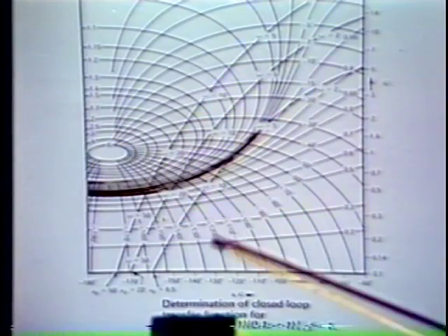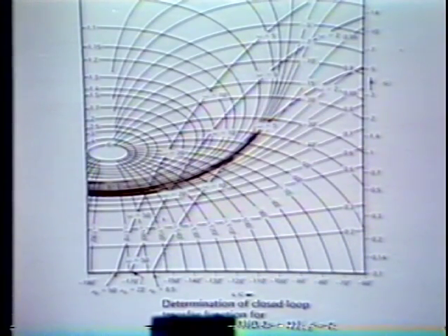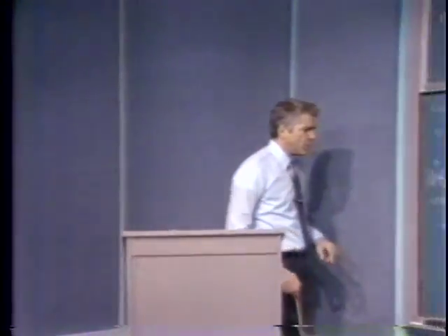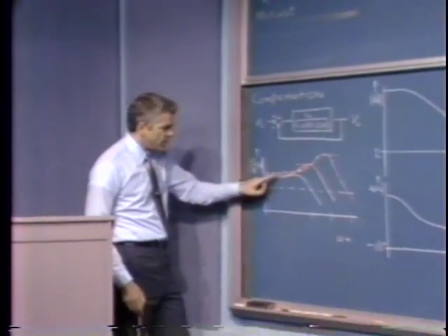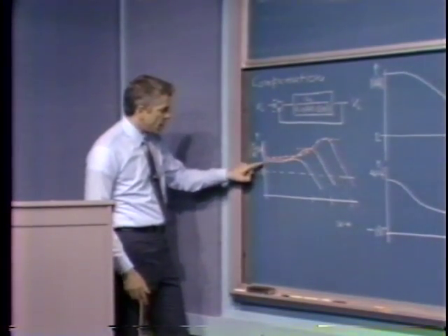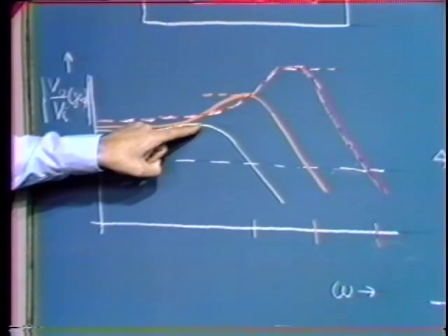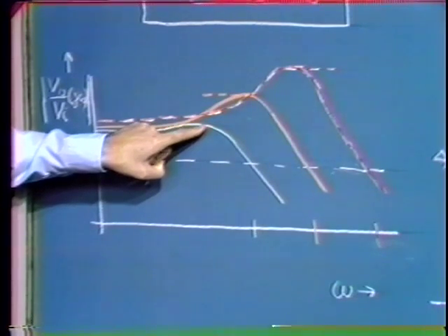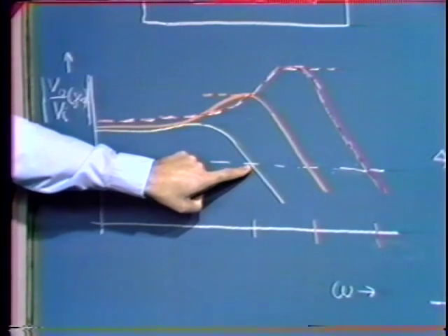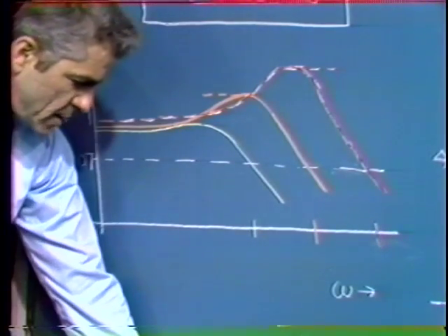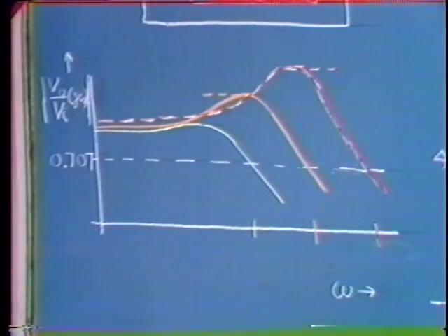The magnitude of the loop transmission is small compared to 1, and the closed loop gain then is just about equal to the forward path gain. So we can plot the closed loop response of the system for that case, and we've done that here. We start out, this would be about 0.9. The magnitude peaks up just a little bit, reaches a magnitude of about 1, as we saw from the Nyquist construction, drops off to 0.707 or 0.7, and we said that that occurs at a frequency of about 10.